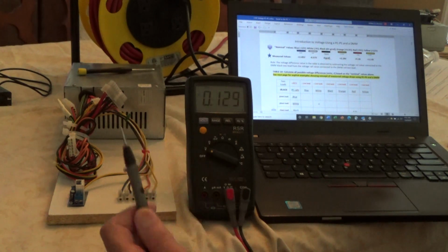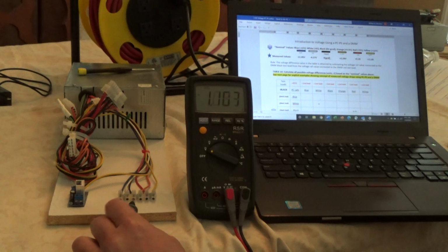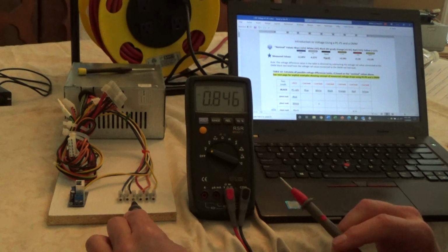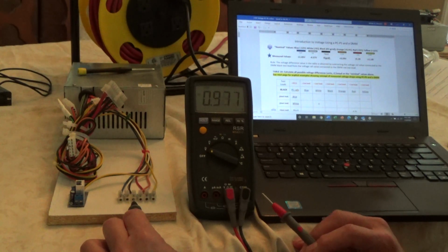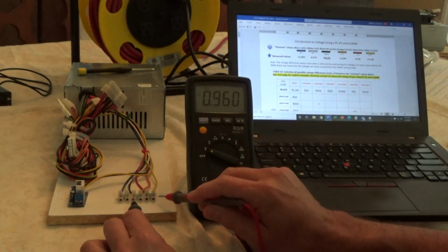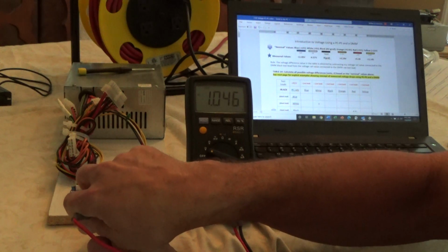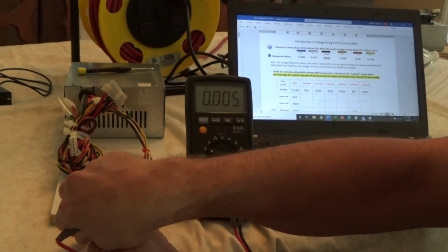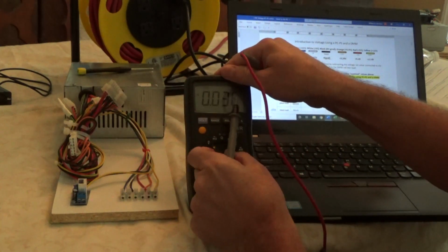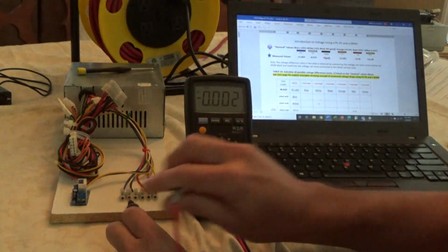We're going to put the black probe on ground. Then we know what every rail is, every voltage value with respect to that ground, that 0 volt level, which is tied to Earth. And you can read about that if you'd like to look it up. What's a ground? What does that mean? Okay, now watch this. I'm going to start with the yellow wire. Let's start with the blue. Let's go in order. So if I touch the blue rail with the probe, we see, whoops, I got it on AC. Sorry about that. I got to put it on DC voltage. I'm glad I did that so you can see. You've got to have your meter configured correctly.